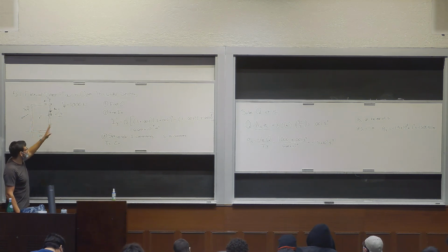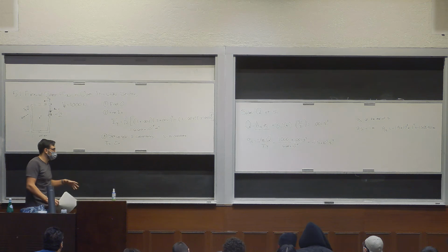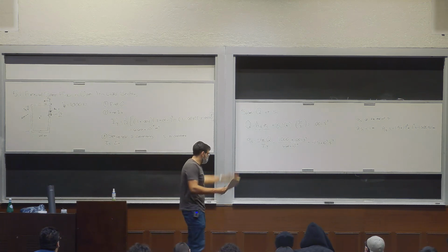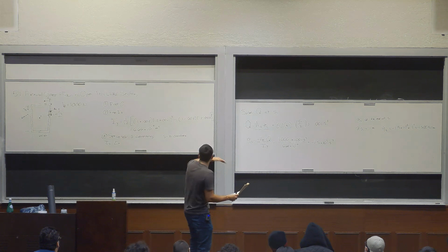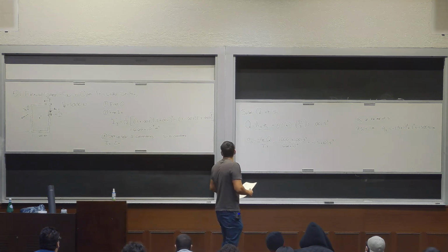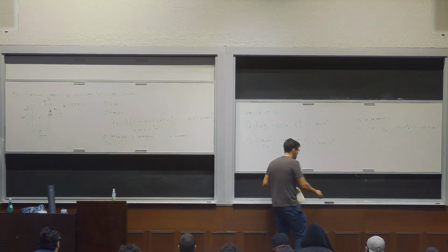So if S1 is pointing up and we got a negative, it means that the real shear flow is pointing down. We'll draw that at the end, so just keep that in mind. This is basically the entire process, but now we're going to keep going for S2 and S3 and so on and so forth. So I'm going to erase this. Hopefully everybody got it.